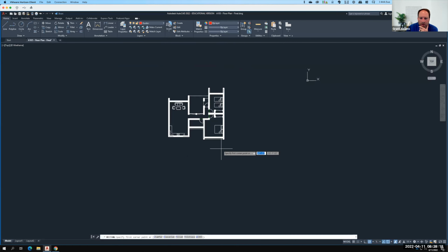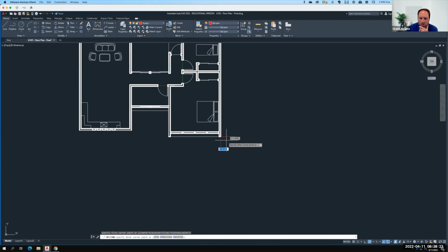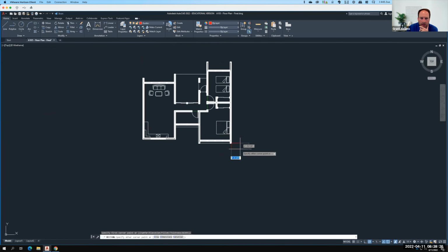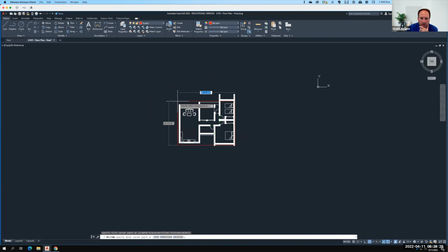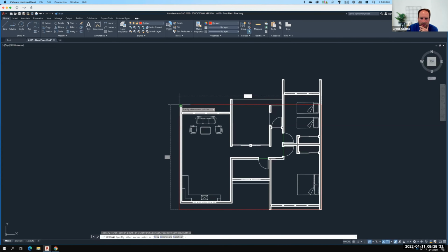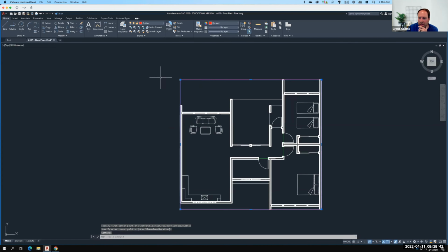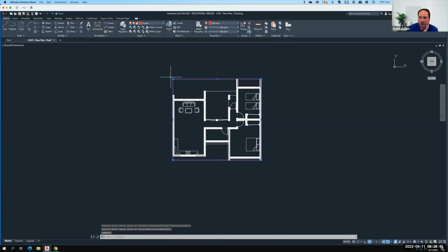And what I mean by a bounding box is I'm going to draw a box that completely contains my whole object. So this would be the lower right corner of my building. And the upper right corner of my building is a cross between this line right there and this little protrusion right here. So if I set 2 points there and I find out where they meet, there they are. This red rectangle is essentially the bounding box of my building, but it's also the planes on which I'm going to draw my elevations. So I have that set up.